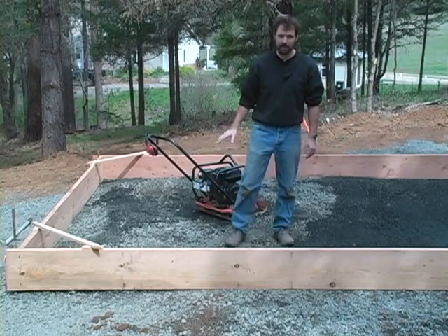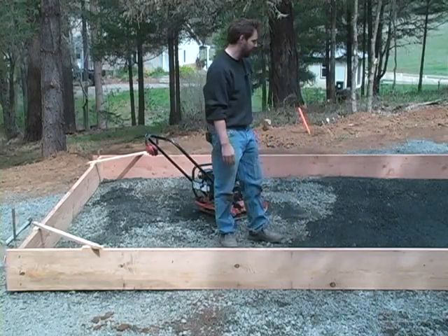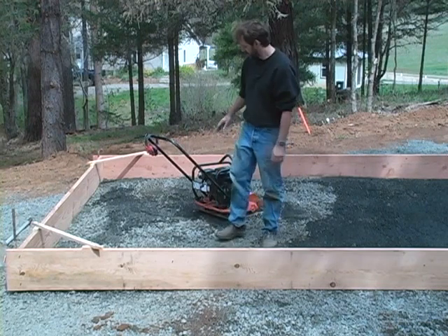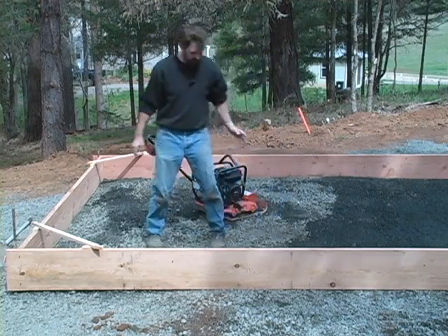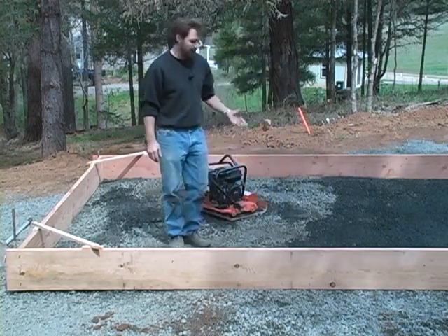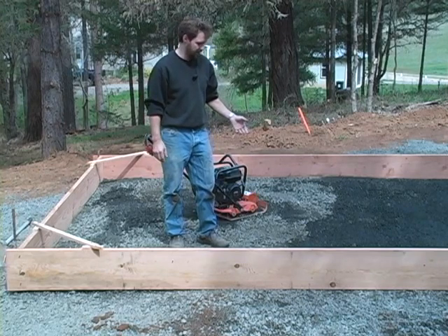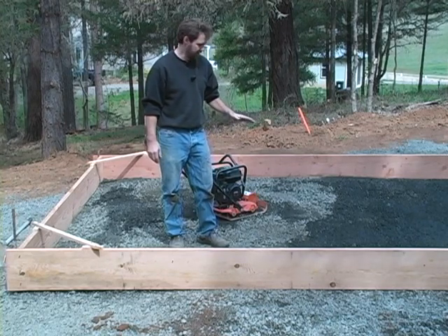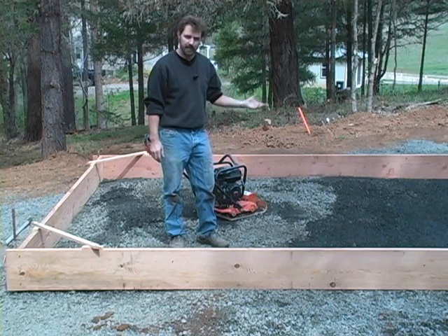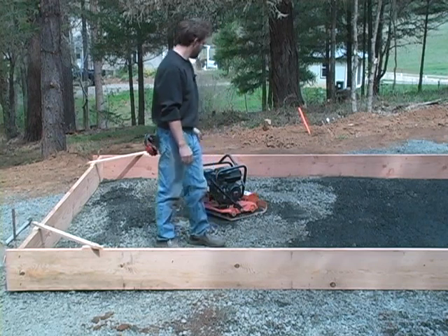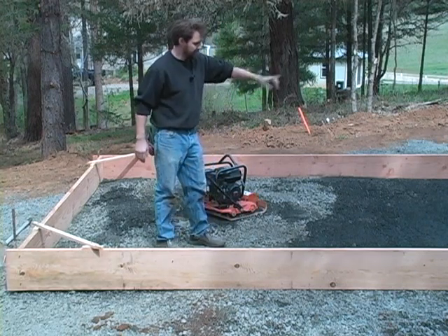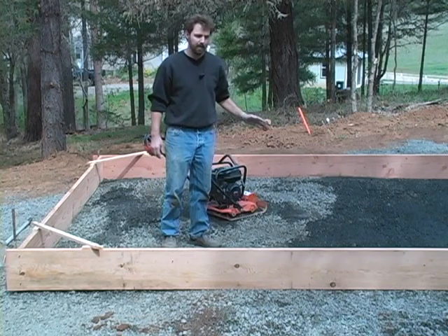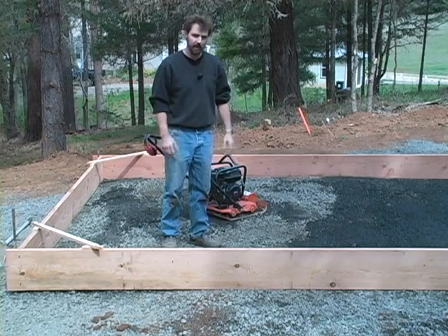Now we've got all of our gravel screeded off to the basic height where we want it, but it still has to be compacted. So I'm going to use the plate compactor, and I'm going to do a number of passes on this. Again, we've been going in about 2 to 3 inch lifts here, so there's not a whole lot to compact, but this is the final bed before we get to the next layers of the assembly. So I'm going to go in at least 2 different directions. I'll probably go over this entire slab about 3 or 4 times to make sure that it's fully compacted.